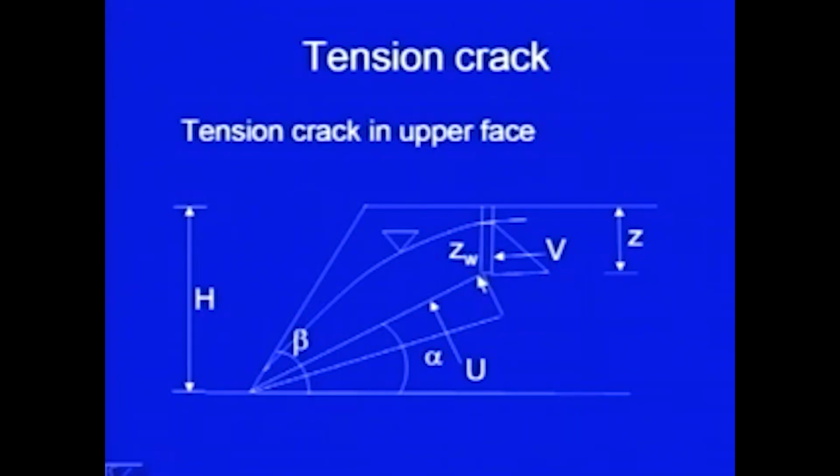And then this joint plane or the fracture plane is extending from the toe to this point, and our assumption is that here the variation of the water pressure is linear, it may be non-linear also. So, we have taken a triangular variation of the water pressure. At this point, the ordinate of the water pressure diagram will be the same as this one.